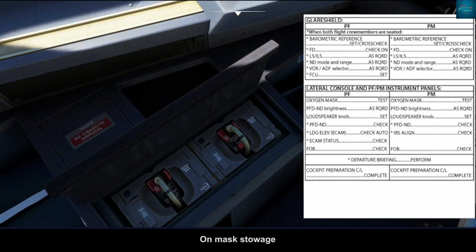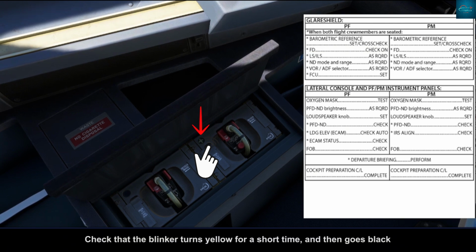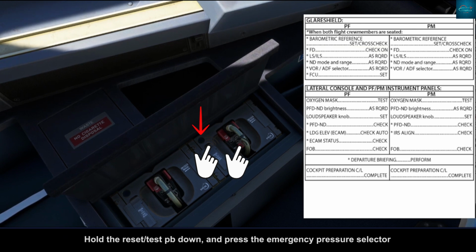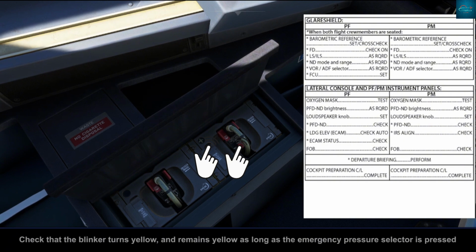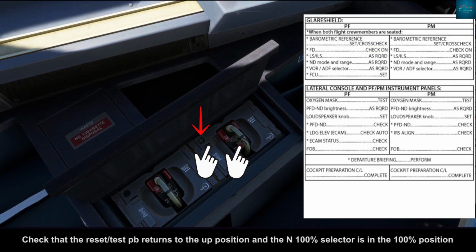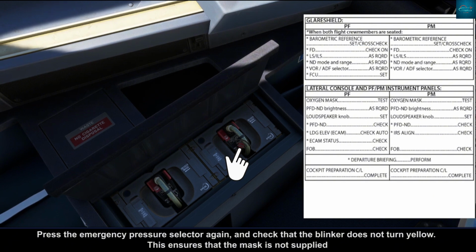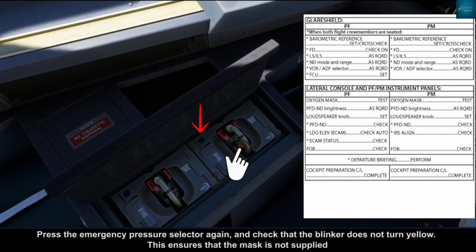On mask stowage, press the reset test button in the direction of the arrow. Check that the blinker turns yellow for a short time and then goes black. Hold the reset test push button down and press the emergency pressure selector. Check that the blinker turns yellow and remains yellow as long as the emergency pressure selector is pressed. Listen for oxygen flow through the loudspeakers. Check that the reset test push button returns to the off position and the N/100% selector is in the 100% position. Press the emergency pressure selector again and check that the blinker does not turn yellow. This ensures that the mask is not supplied.